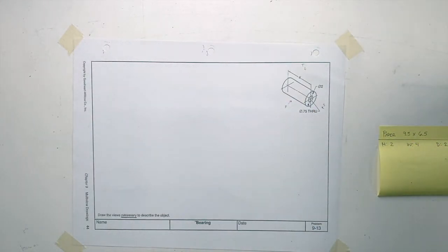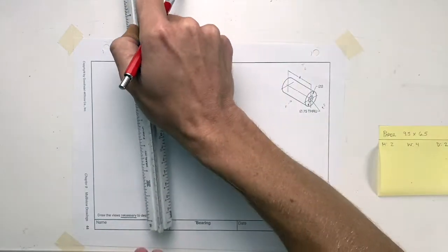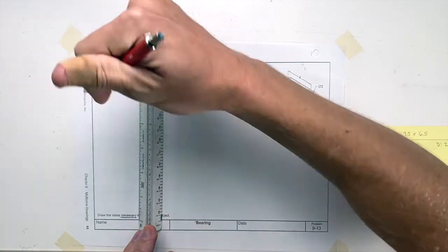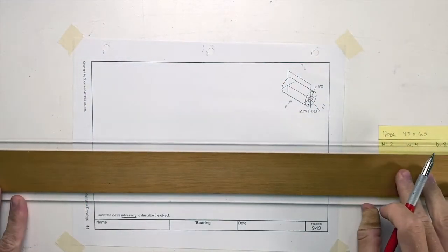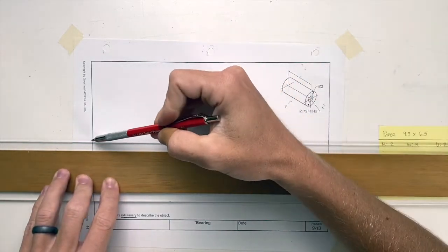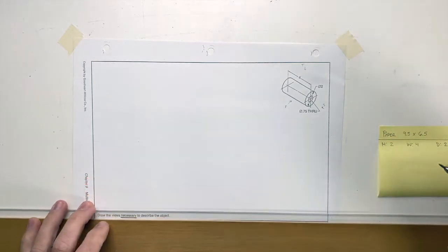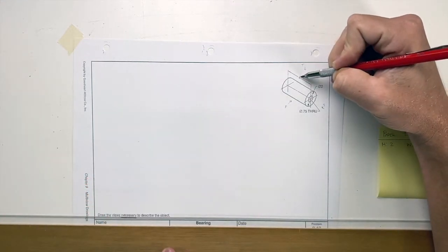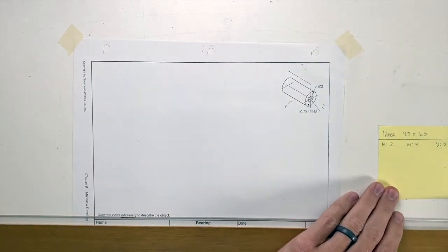So if my paper has a drawing space of 6.5, half of 6.5 is 3.25. So basically, the center of my view is a circle or a cylinder, so it's going to be right along that construction line. Then I'm going to do the math for my horizontal spacing. So I have 4 inches plus 2 inches, that would be 6. So let's do this on the paper.